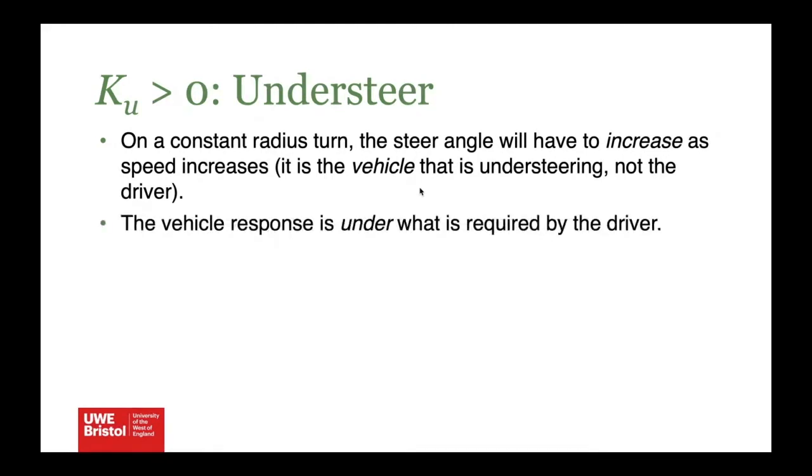The vehicle response is under what is required by the driver. So the vehicle, like I said, is trying to wash out, trying to make the radius bigger, and so the driver has to apply more steering to get the vehicle to do what he wants it to do.